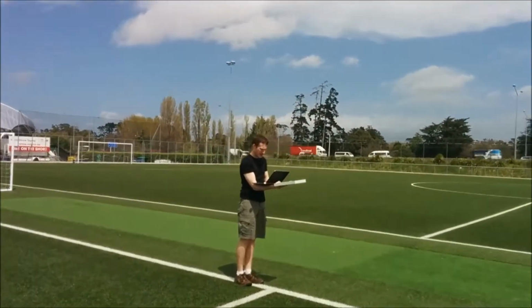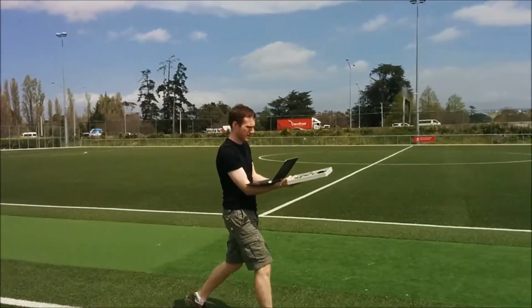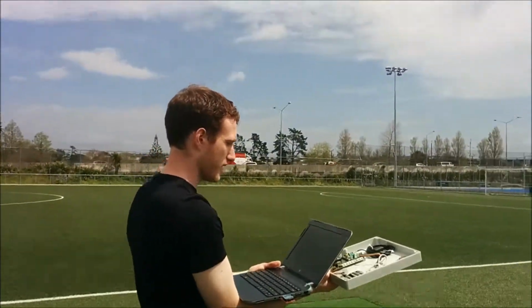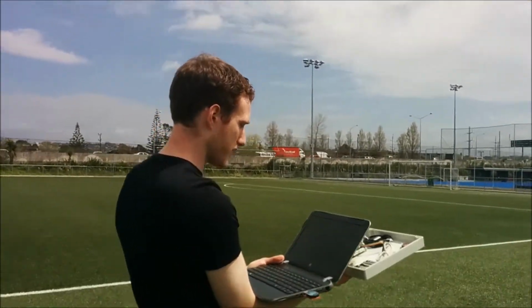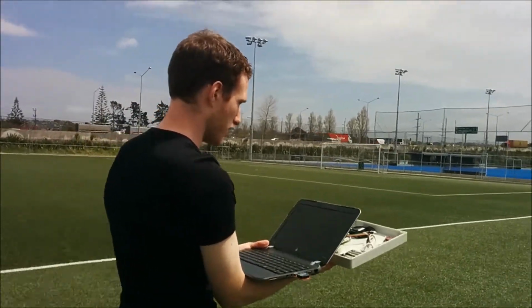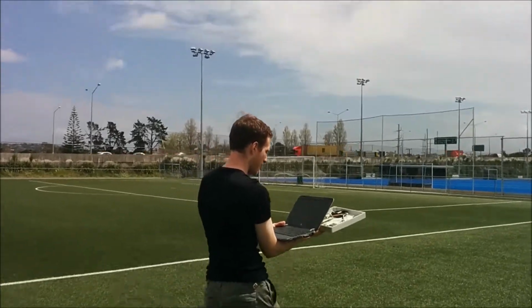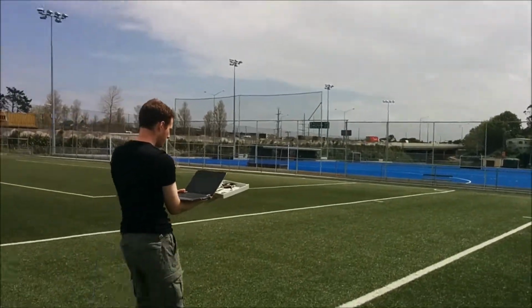The first stage is where the accelerometer is sampled and the reading is fed through a prediction state matrix. It is then compared against an observation variable, which in this case is the GPS. These two values are compared using weightings, and then an estimate is retrieved for that iteration.